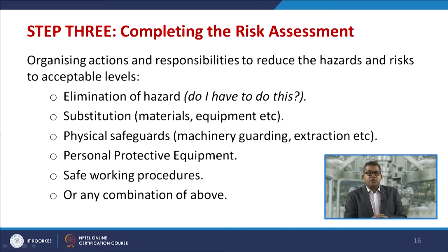Then go for substitution of materials, equipment, etc. You must adopt the protocol related to the physical safeguarding of machinery, guarding, extraction, etc. Sometimes, if you go to an industry, you may see that all kinds of pulleys are guarded by covers. These are called physical safeguards. You must go for personal protective equipment like headgear, goggles, gloves, splash suits, etc. You must adopt and devise safe working protocols.